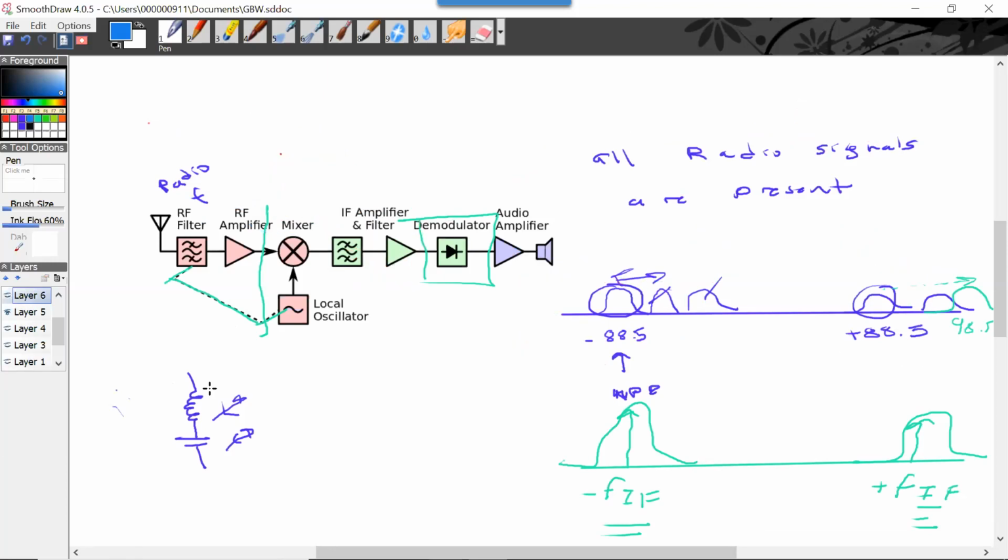You've got to take your original data, multiply it by a cosine, you get positive and negative, and you convolve that. So now you've converted your data to a higher frequency, right? And then you got to transmit it. And then really you need an antenna to get it, a bandpass to filter out all the other signals, right?